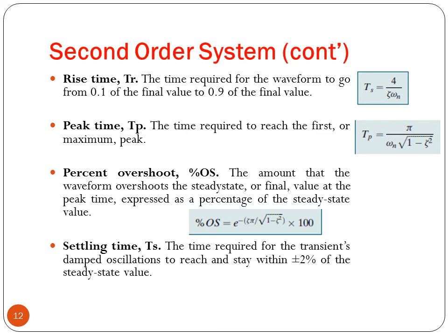In fact, this value is very important. Why? Because let's consider that we have a pump whose input voltage is between 0 and 6 volts as specified by the data sheet, and usually it works on 5 volts. So if the overshoot is above 20%, at a certain time it will require more than 6 volts. We will notice that the life cycle of this pump will be smaller than the expected one, because it requires more voltage or more power than the one it's allowed to have.